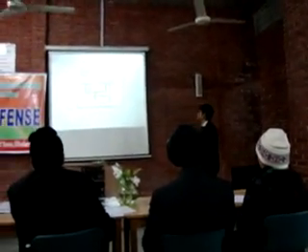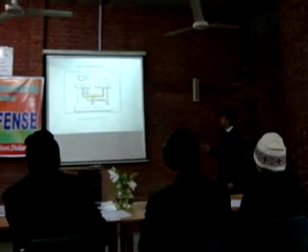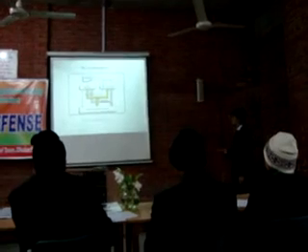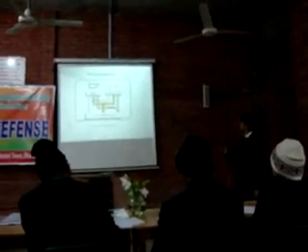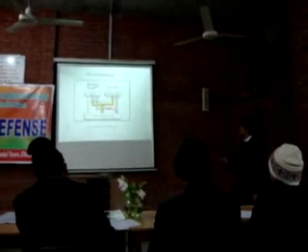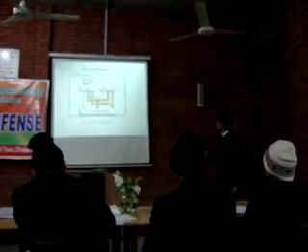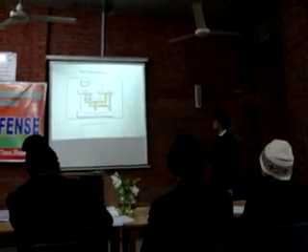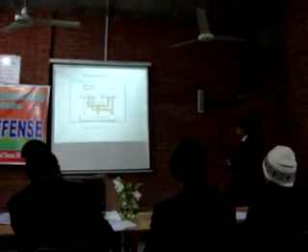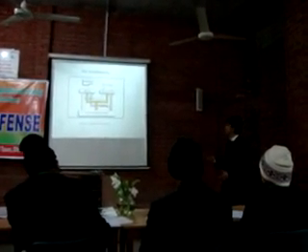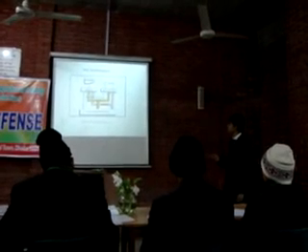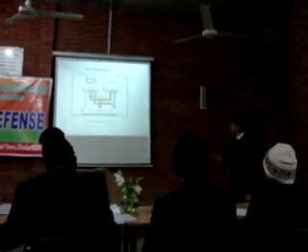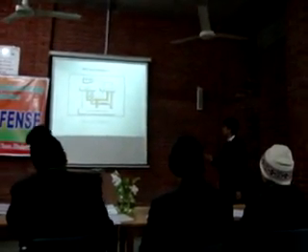This is the PLC architecture. There are four parts here: program, memory, input-output, and central processing unit. The memory, central processing unit, and input-output are internally connected by address, data, and control buses. The input-output devices are connected to the real world. What is the real world? Real devices are connected here, like sensors, HMI devices, and speed detectors. This type of device is connected here.